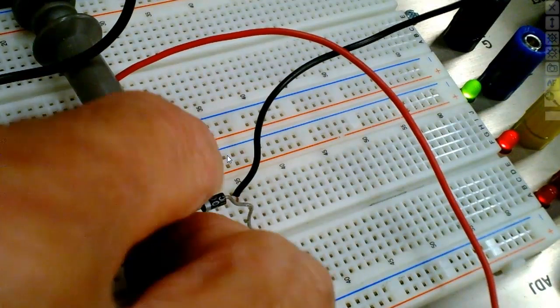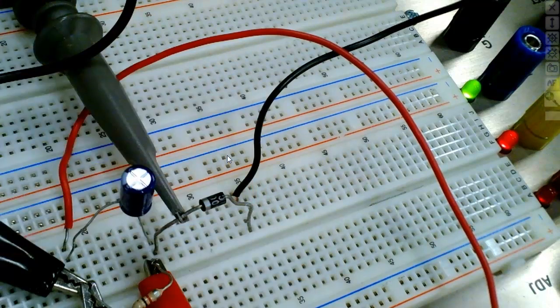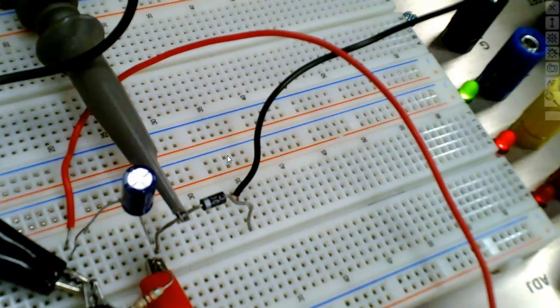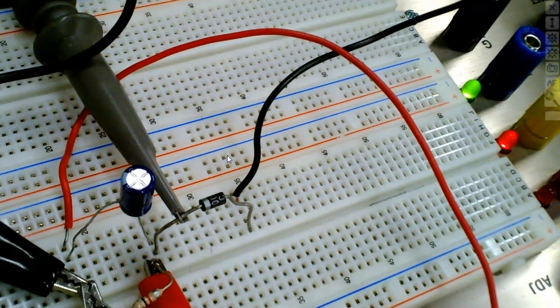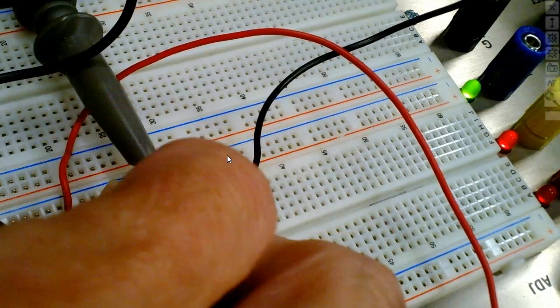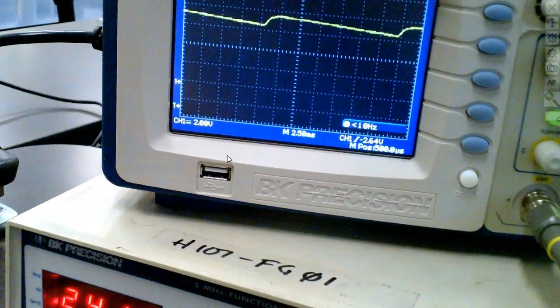So now it's halfway rectified. Okay. We call it unregulated, which means the output varies with the load. So what I'm fixing to do is come over here and we'll look at my scope, and all I'm going to do is put another resistor in parallel. I'm just going to touch it.